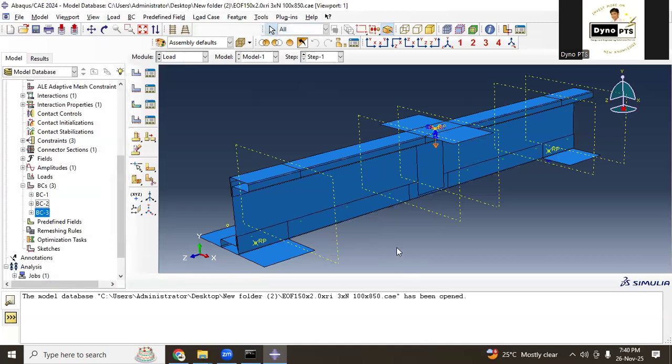Done. It is completed, and next we have to find out experimentally, at displacement gauges, which are provided here on the right side and left side, longitudinally as well as in the transverse direction. Displacement is also measured here, at the middle of the flange.